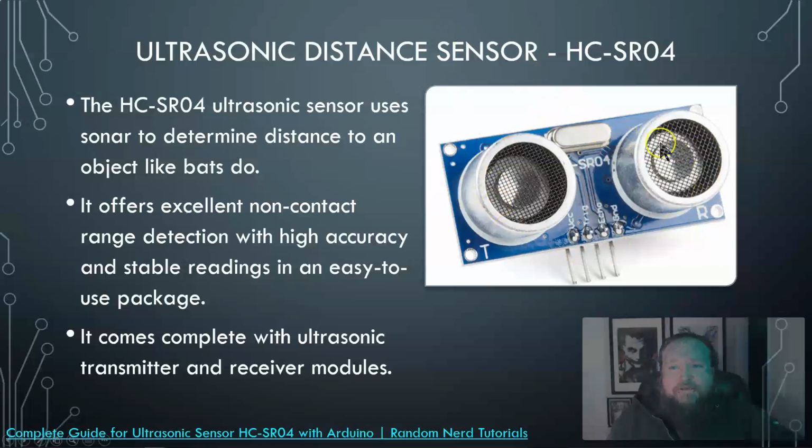So you're getting an entire circuit and everything. You can see that you have this board, you have the conductive lines below an insulator material, you have exposed pins, you can see markings on this one, which is giving you ways to understand what's there. We can already see that we have G and D for ground. Well, this pin's got to be something negative or ground. I'll give it away that the VCC means power. And then we just have these two other pins, meaning trigger and echo, which we need to learn more about.